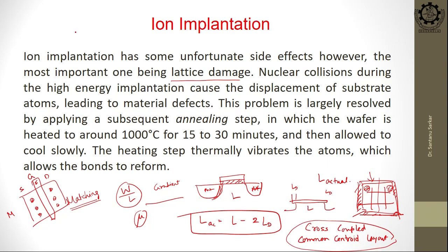Suppose you have metal 1 and then you will be having higher metals depending on your technology. Some technologies have 3 metals, some have 5 metals, some have 7 metals. So, metal 1, metal 2, metal 3 generally go up higher in length, each one at a particular level. Okay. So, the lowest metal, these windows, is generally M1.